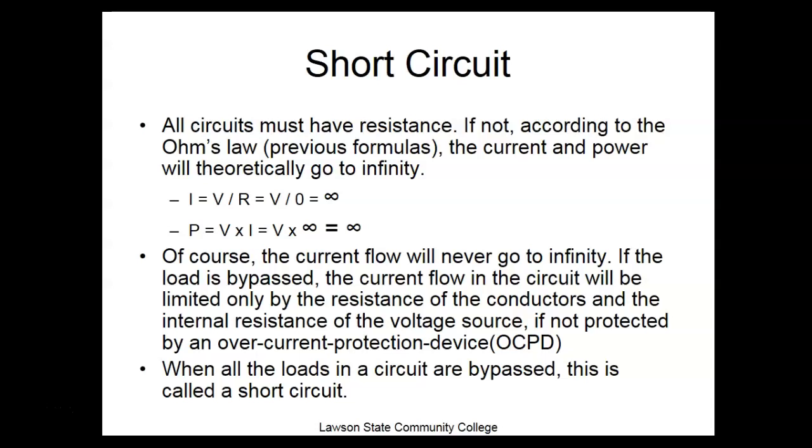All circuits must have resistance. If not, according to Ohm's law, the current and power theoretically would go to infinity, which it can't. Of course, the current flow will never go to infinity. If the load is bypassed, the current flow in the circuit will be limited only by the resistance of the conductors and the internal resistance of the voltage source. So short circuits are what we protect against.